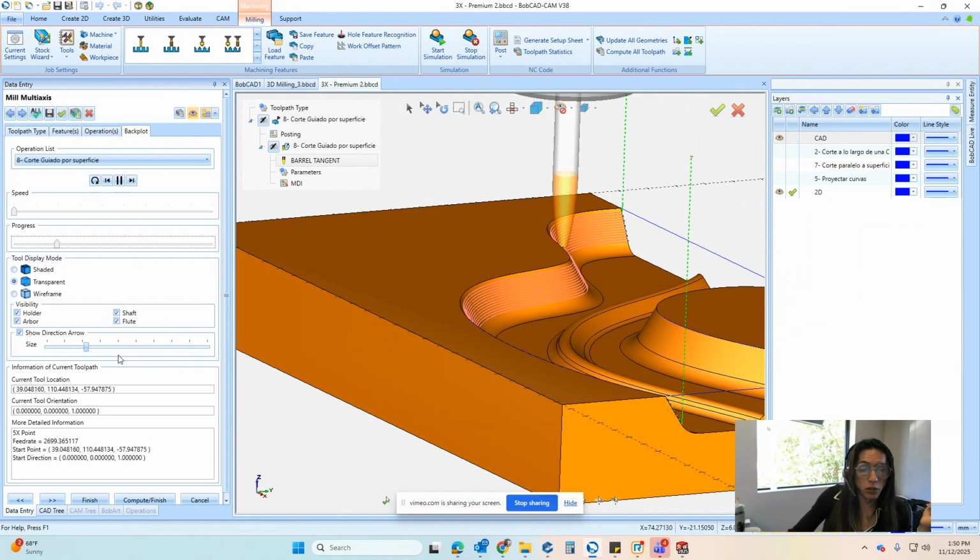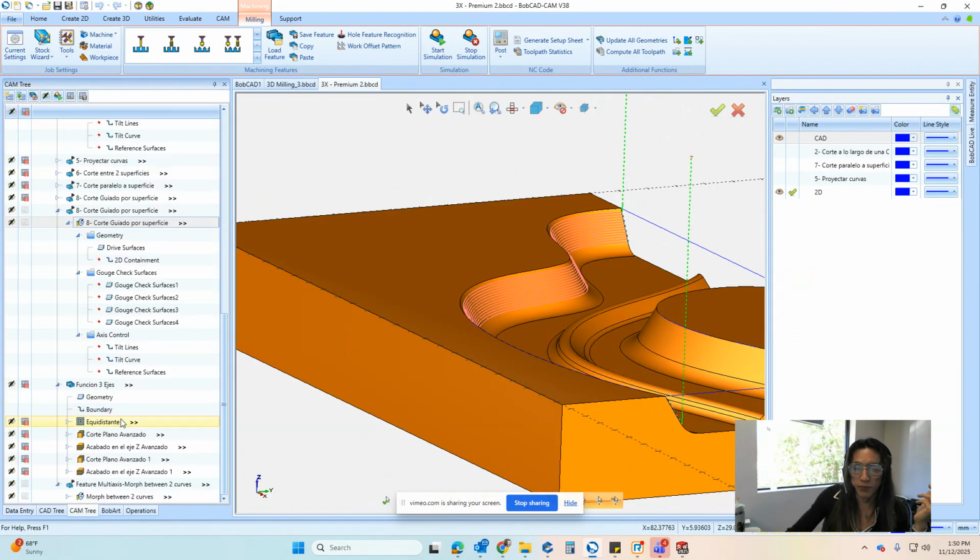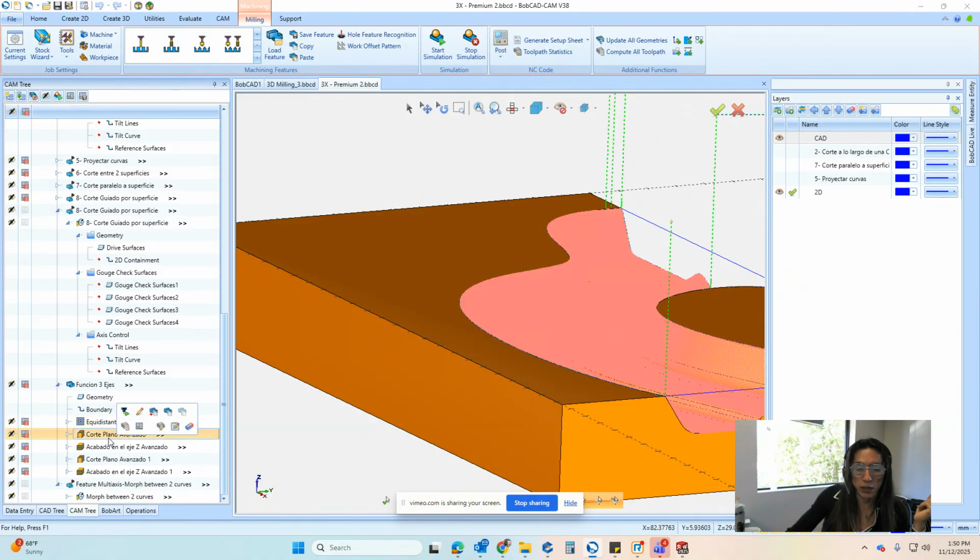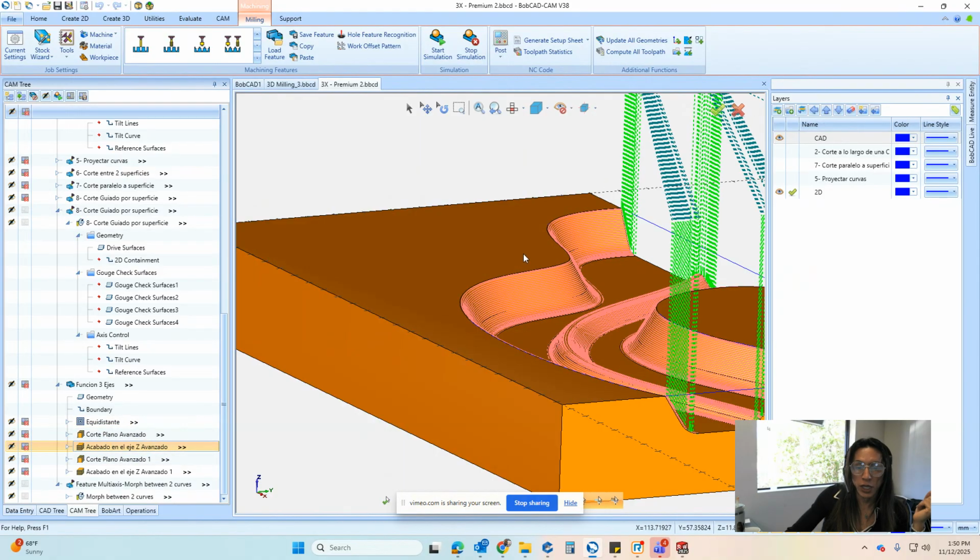And again, they're part of our premium toolpaths. I really recommend looking into that, because you're going to be able to get away with bigger step overs, less machining time, and better quality than using an actual Z level finish with a smaller step over.